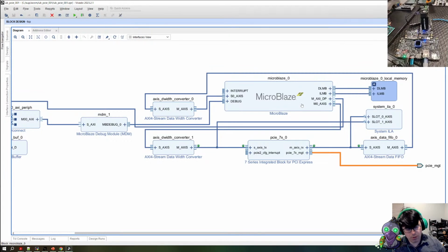This is going to be really cool because we'll be able to look at the low level TLP packets and respond to them via software rather than having this hardened core, which is in most systems. It's not going to be terribly responsive, but if we keep the packets small and plenty of space between, we should be able to play around with PCIe and manipulate how the TLP packets interface with the root complex.